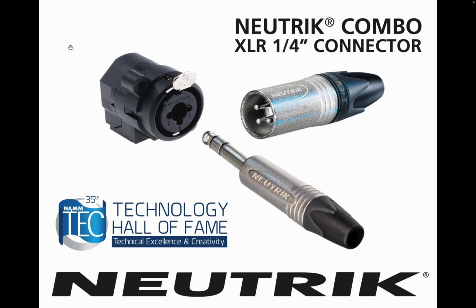Okay. Now, some of the XLR connectors also have a 1/4-inch plug smack dab in the middle, which makes them look kind of funky. But you'll still see the left, the right, and the bottom pins of a standard XLR connection. It's just that the 1/4-inch plugs right into the middle of it, and it's supposed to serve the same function. You'll notice that this 1/4-inch connector has three separate fields on it, separated by an insulator washer. And so that's also designed to provide phantom power.